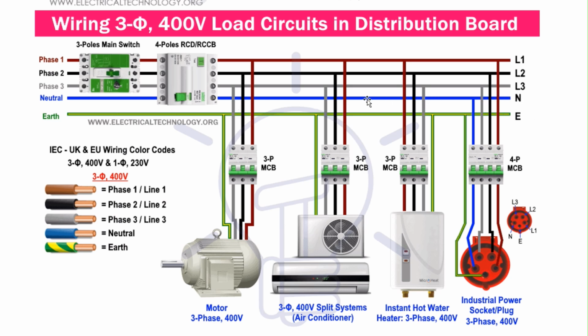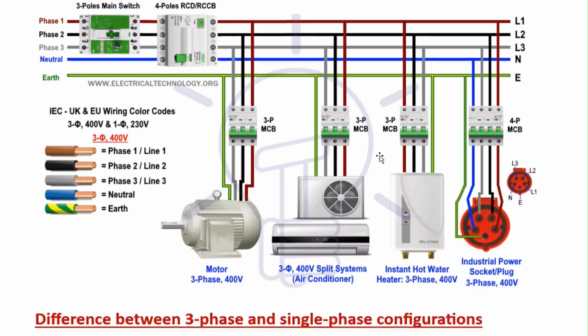The neutral wire is sometimes black in the Indian situation, and after RYB these three colors are fixed for three-phase supply. The voltage between any of the phases and the neutral is 230 volt, so it can be directly used for loads like single phase motors, single phase supplies.